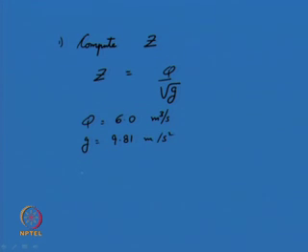So your section factor is identified as 1.916. What is the non-dimensional form of this Z? You just evaluate Z by b to the power of 5 by 2. You know the given value of b is 2.5 meter.